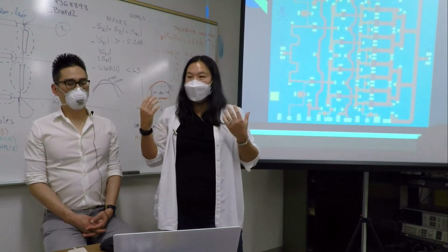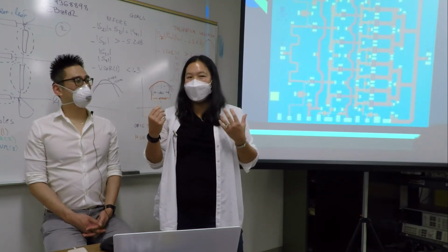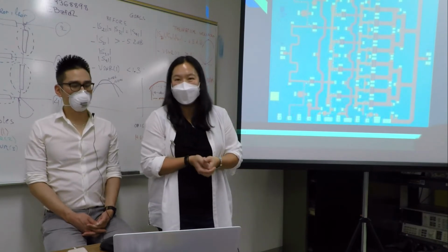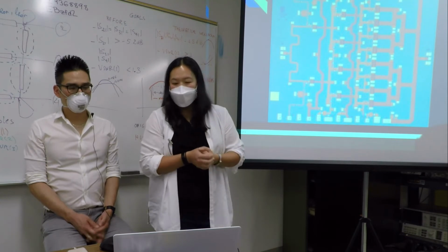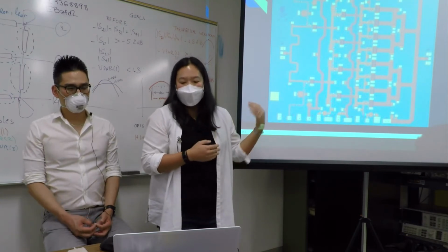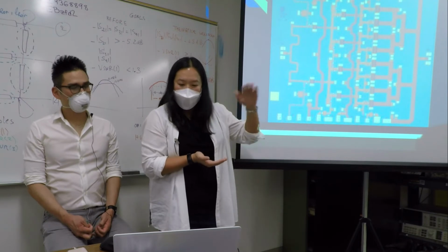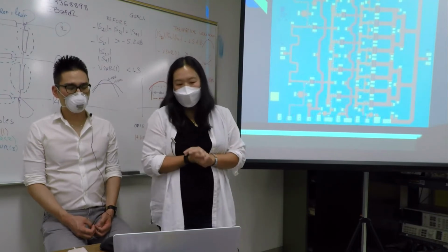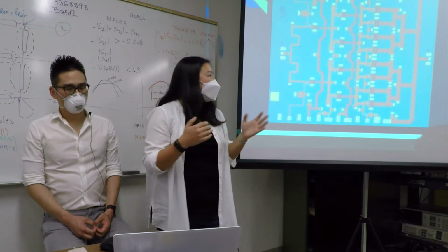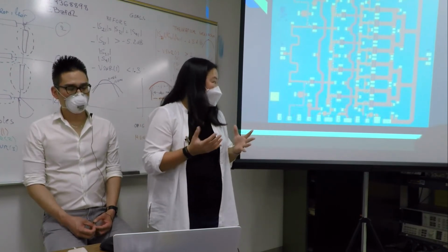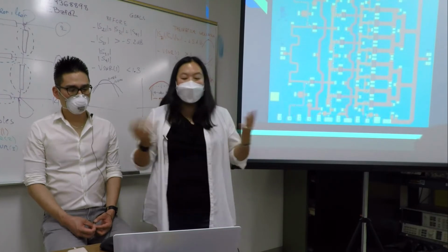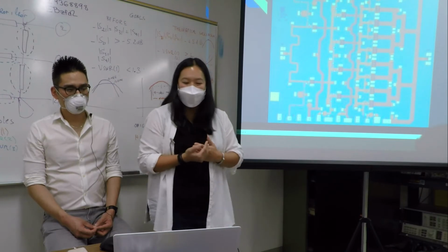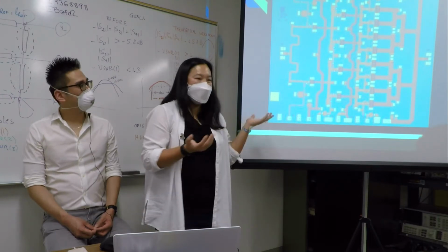So typically with a foundry, for the cost of making these, you have to have your wafer mask. You're going to learn about masks in 132C when you make your own circuits. In industry, you will have a mask for each layer of this circuit, this is multi-layer here. The total cost for the masks for one of these designs will probably be about 80 to 100K, and then each wafer after that can be 20 to 30K. Then you chop up each die from your wafer, and you can get your per-die cost.